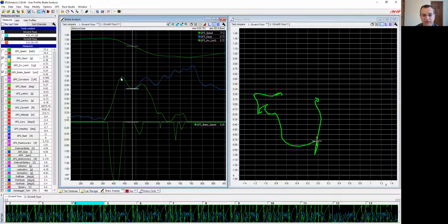That's the number one thing of seeing this dip, where G sum and long G both dip together before they separate, right? That's kind of the key characteristic we're looking for, where they both dip together before they separate. That means the braking pressure was coming off before you're starting to turn the wheel and turn into the corner. Hopefully that makes sense to you guys.